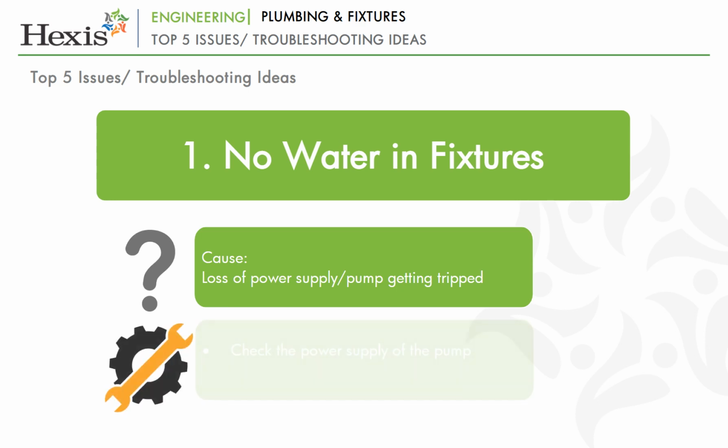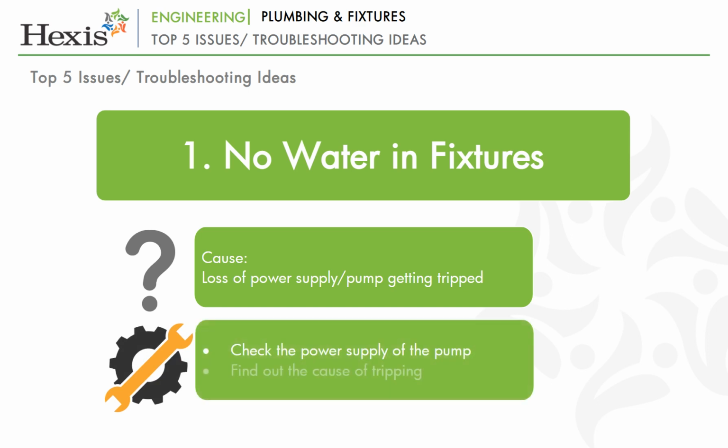Troubleshoot idea. Check the power supply to the pump. If the breaker is tripped, try to ascertain the cause of tripping and rectify. Check all valves are open and the lines are clear.